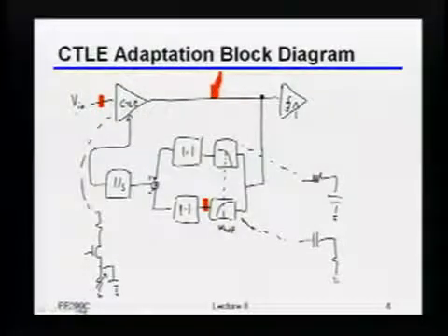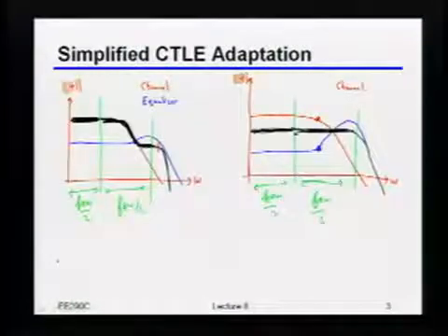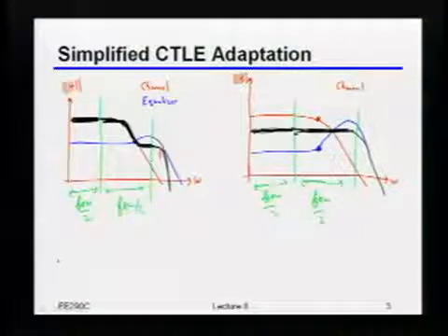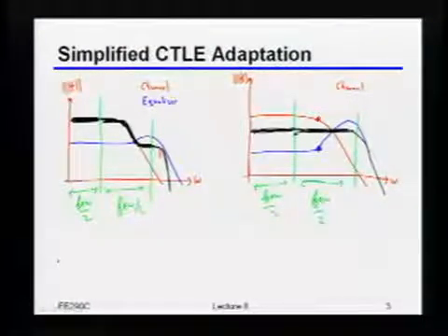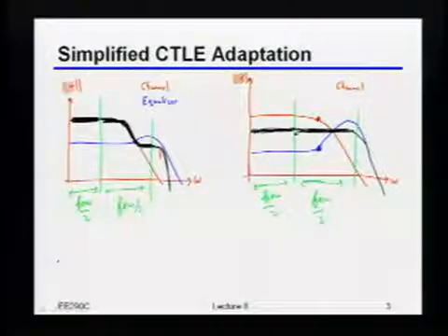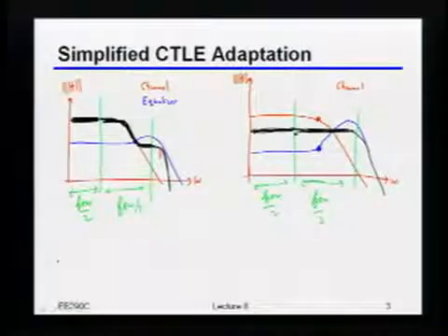Is that the reason why it's 0.48 or whatever? That actually has to do with the fact that you don't necessarily set the equalizer bandwidth to 0.5 of the bit rate or whatever. You set it to 2/3 or somewhere in that ballpark. There's some optimization you run there. Again, I don't think it's actually super critical unless you care down to, let's say, the last few dB or whatever it is.